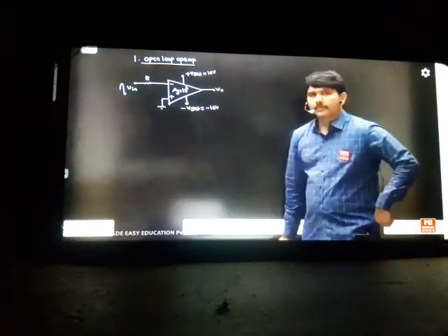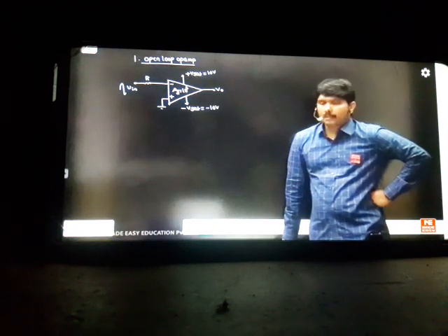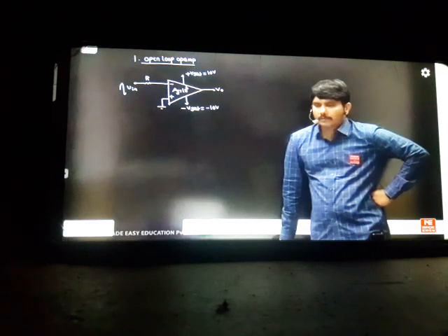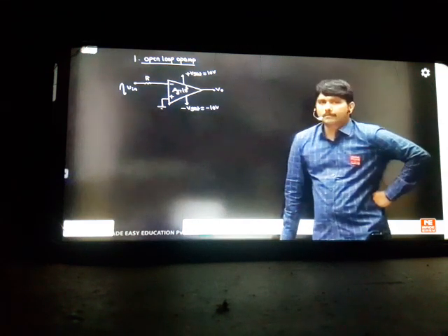AD value is the differential gain, which is our open loop gain we can say. Op-amp gain is AD. We call 10 power 6 the gain I have taken. 10 volts and minus 10 volts are the saturation limits. Okay. The input is a small signal, suppose.